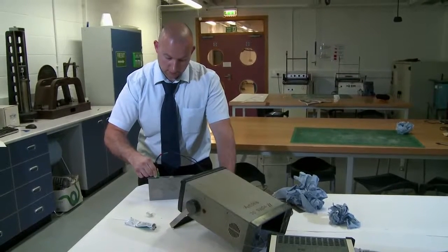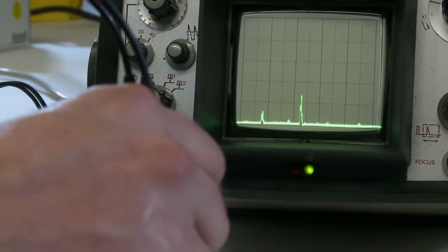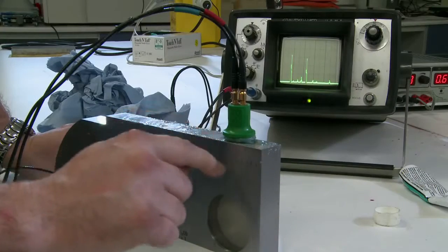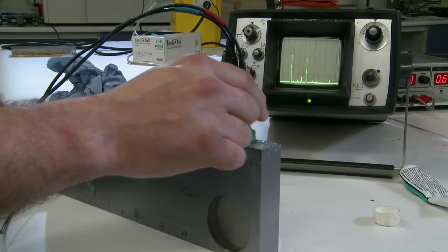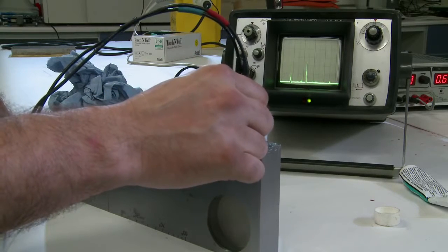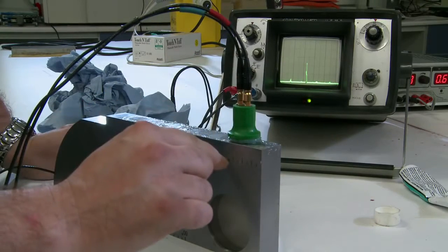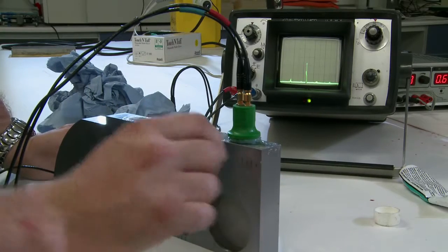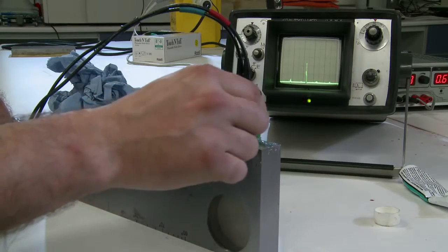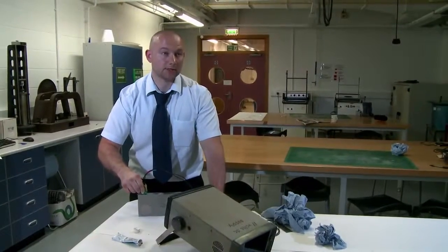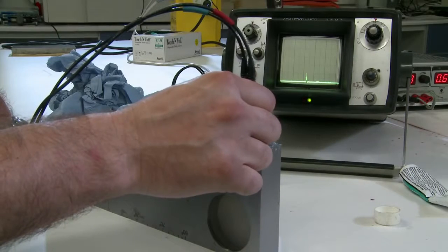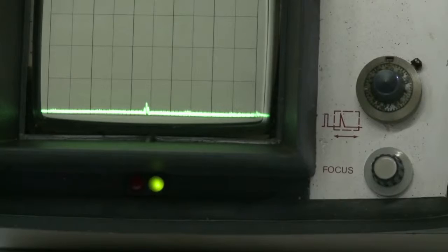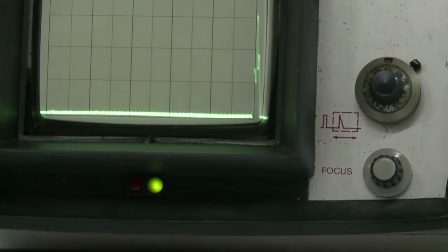As we continue to traverse, we get a reflection at about 15mm, and that is a defect 15mm down from the surface. Again, continuing the traverse, because that's only a small defect, it disappears, whereas we're still detecting this defect that's 45mm down. If we carry on traversing across, eventually the one at 45mm disappears, and then we start getting the back wall signal reappearing at 100mm.